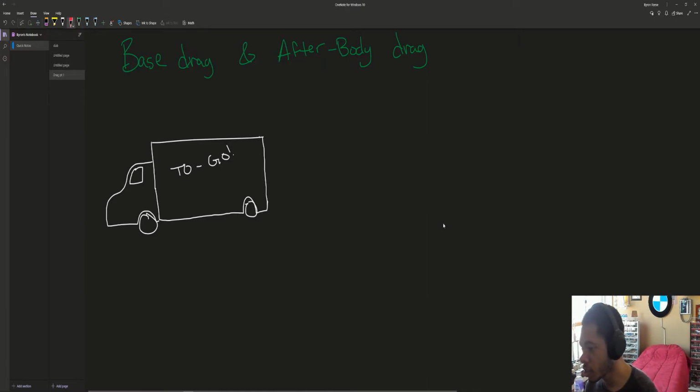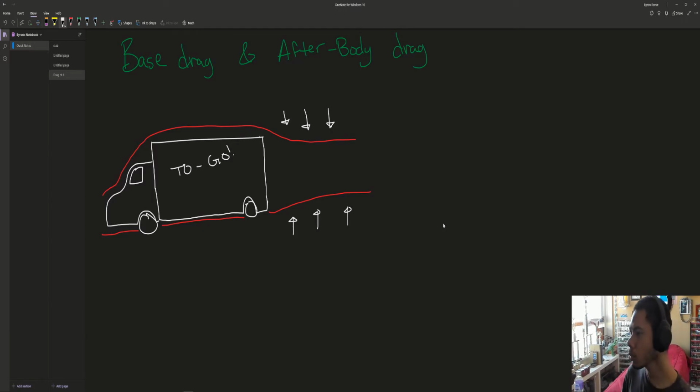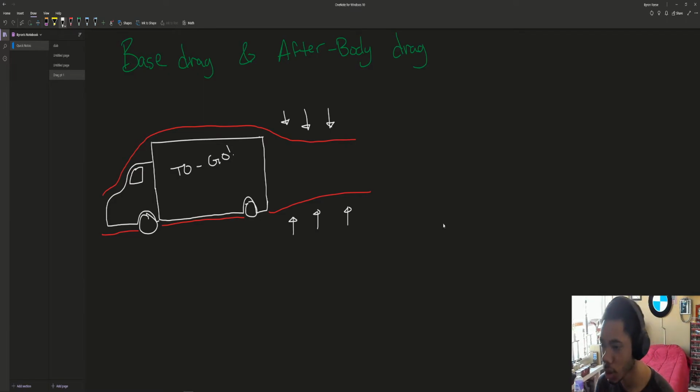As the flow of air moves over the truck, as the air tries to come back down, let me try and redraw that real quick. It's just going to do something like this, neglecting rotational flow that occurs due to the wheels. Remember we talked about the Coanda effect, right? So ambient pressure is going to push this pressure into this region because that's considered a curve. However, the curve is so intense that there isn't enough time for the airflow to come back together, and because of that, it creates separation.